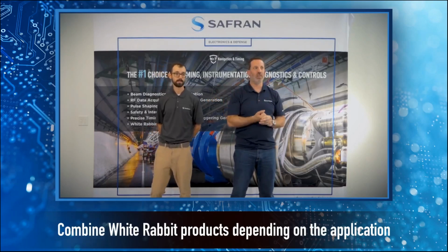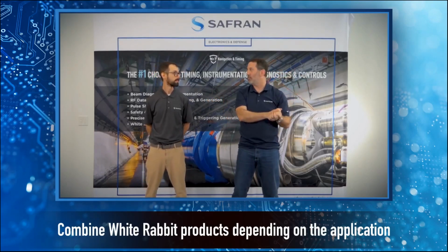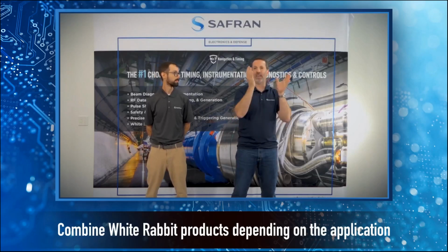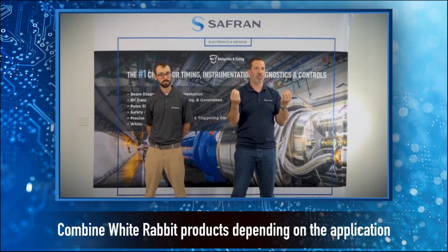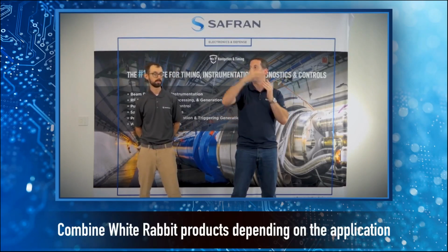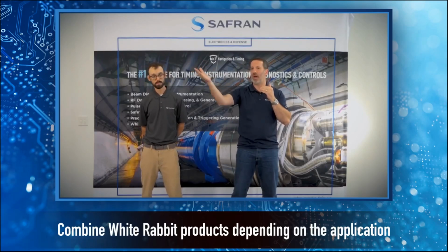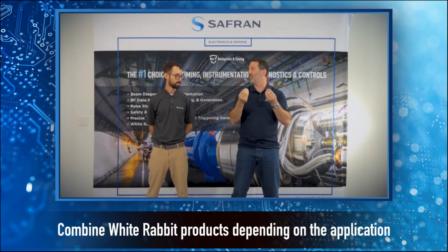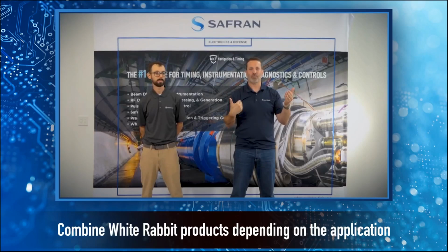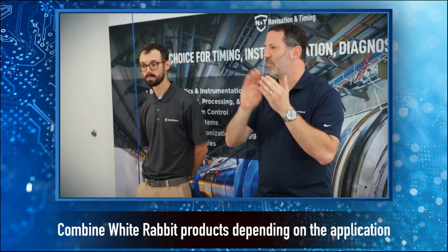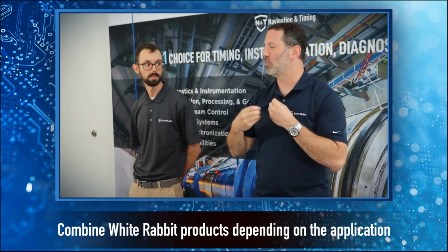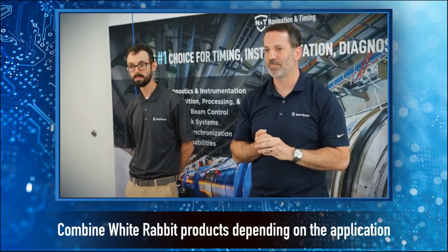So, if I have an issue at my site A that has my reference devices, I can fail over through the distribution chain with my White Rabbit devices from another remote site without losing the fidelity. Coming back to that error budget that you get through distribution, you don't take that hit with having to go to some remote site, because you can distribute that with high fidelity from there through White Rabbit.